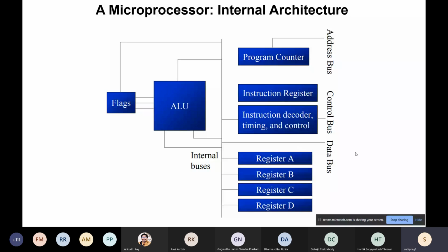So we have started the microprocessor the first time, and data has come. The microprocessor is typically programmed to keep it in the instruction register first, because 0000 was the address, and at that location we must have the first instruction. That instruction may have subsequent data in subsequent bytes, but that is separate; the first location should have the instruction. The first instruction has come from the data bus. Instead of going anywhere else, it will simply come and sit in the instruction register. That means the memory content gets copied to the instruction register. Memory is read and instruction register is written.